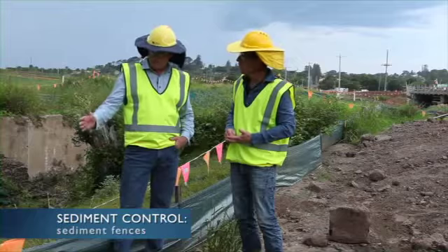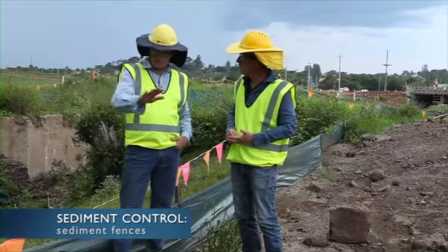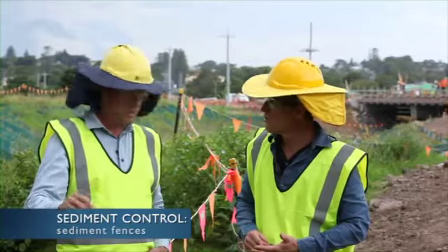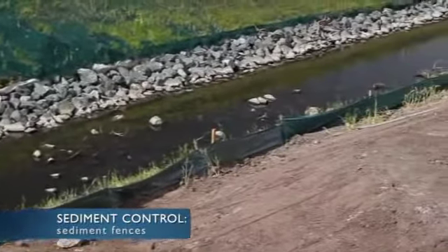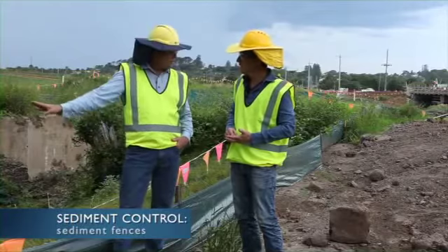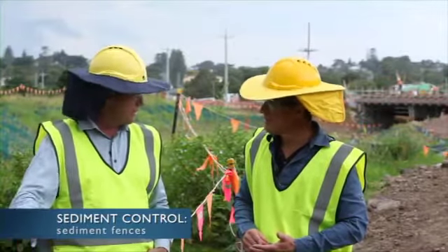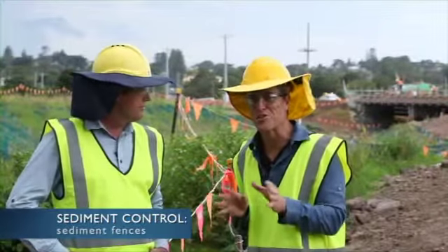So essentially what we want to do is put them out along the contour, and they're designed to take sheet flows, not concentrated flows. The other thing you can see here is they have to be staked at regular intervals. And what's really important for the silt fence is it actually is properly dug in, so the bottom of it doesn't blow out with the rainfall or with the runoff and let that dirt go straight into the creek. So even for the little silt fence, there are design considerations.